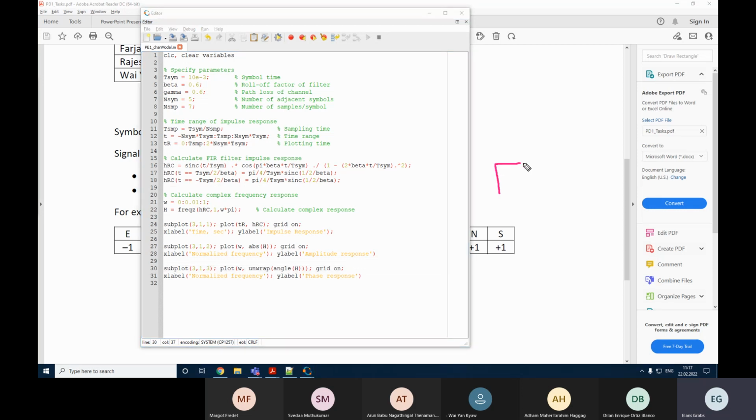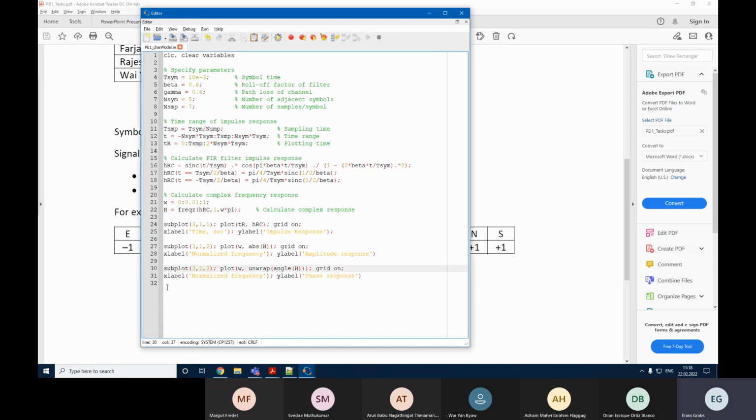Usually we represent these symbols, +1 or -1, with rectangular shape pulses. However, we'll need to make some conversion from these pulses because we cannot really send these pulses in our digital program. We also need some equivalent replacement for them. So in fact, what we are going to do is read samples of this signal, +1 or -1, and these samples are the signal values we will use. I will return to this idea in a few minutes, but first let us say that this is task 2, and this was task 1, to construct this.